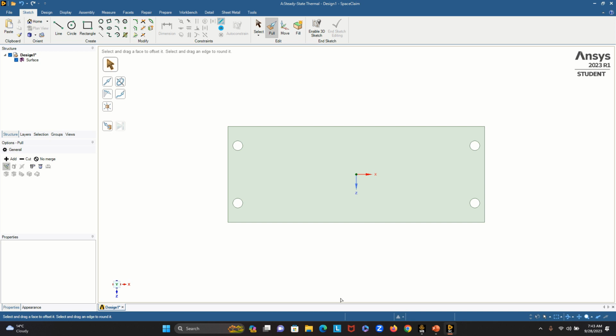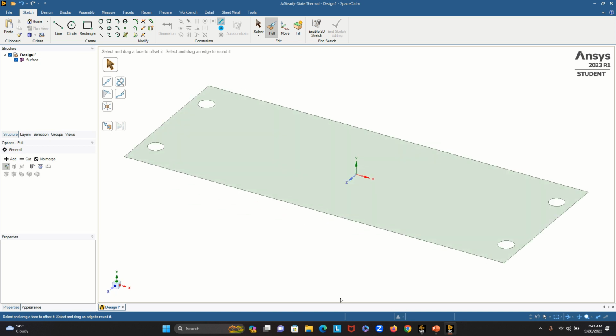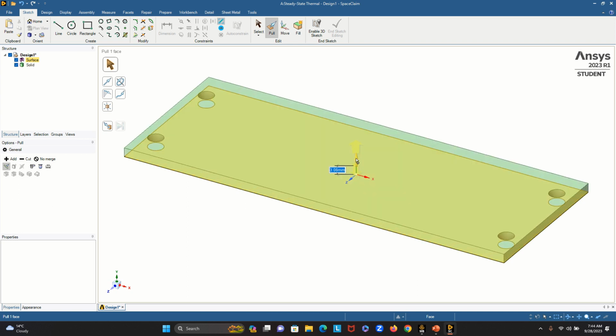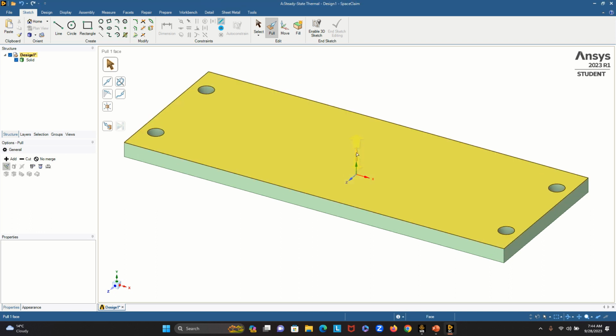I'm simply gonna click the H button on the keyboard, so that the geometry itself will be in a shape that I can easily select and extrude to the desired base thickness. I'm gonna select the y-axis and pull it up, and I will also hit the space button on my keyboard in order to define it. I'm gonna give it 5 mm as well for the thickness.